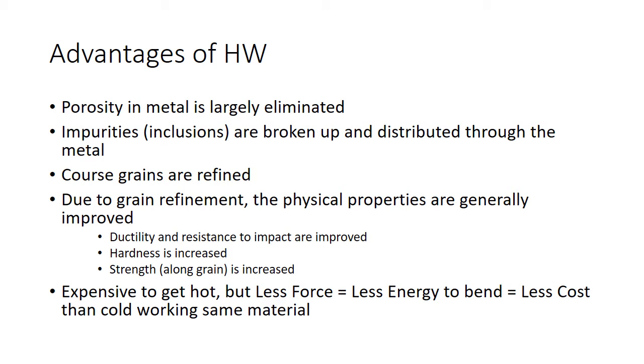So it has advantages in the parts, and if you were comparing a particular material, say a half-inch piece of steel that you wanted to bend, you could bend that with cold working, just like Superman bending it. But it would take a lot more expensive equipment because it requires a lot more power to do that.